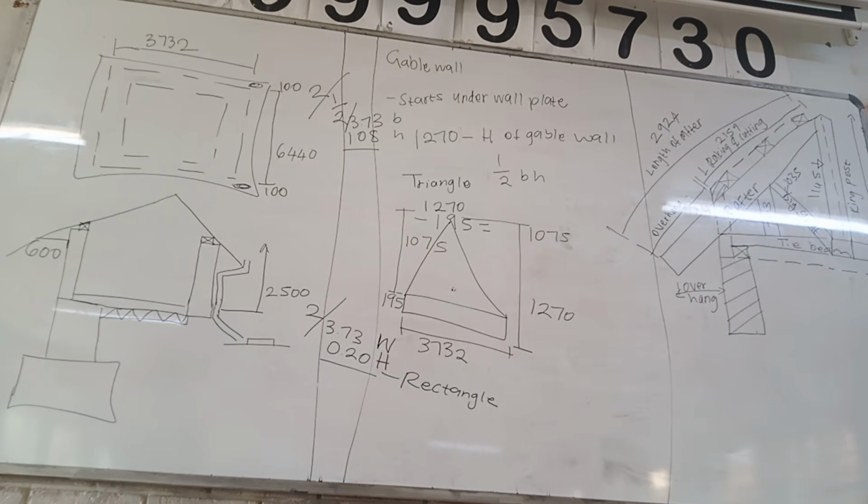by 76 rod eave purlins, 600 millimeter overhang at eaves, 100 millimeter overhang at gable ends, fiber cement sheet roof covering, fiber cement ridge piece, 15 millimeter by 200 fiber cement fascia board, and 10 by 200 barge board. Roof pitch is 30 degrees, brick wall 220 millimeter thick and faced externally.